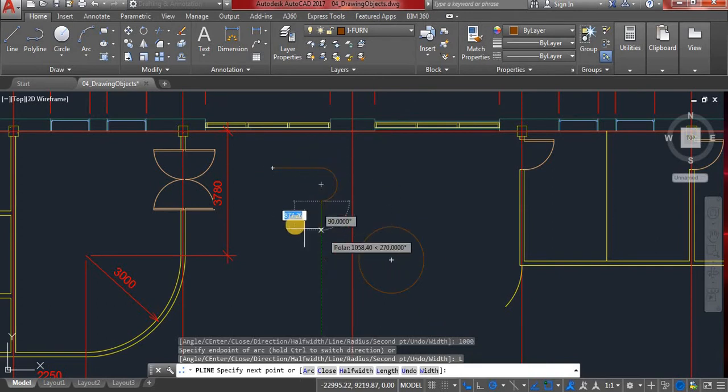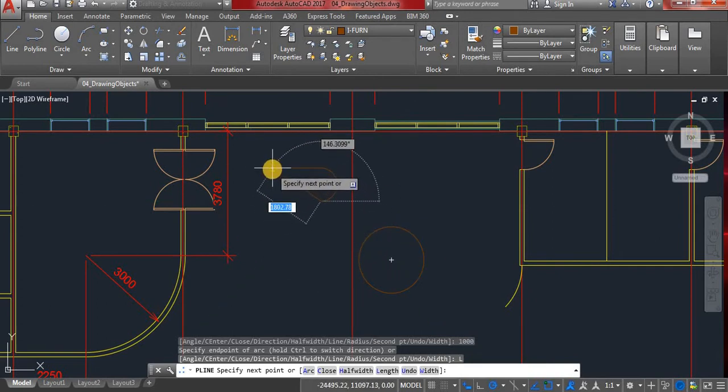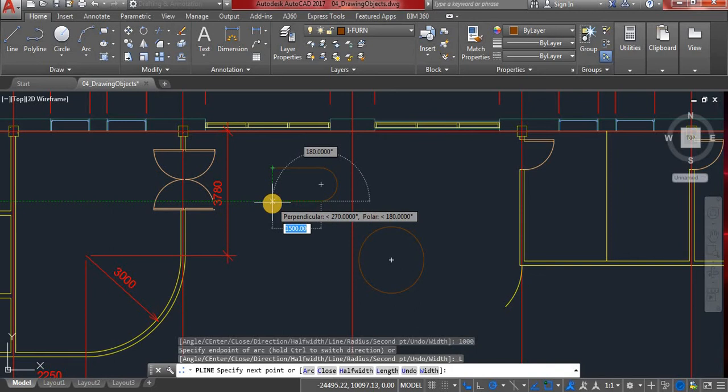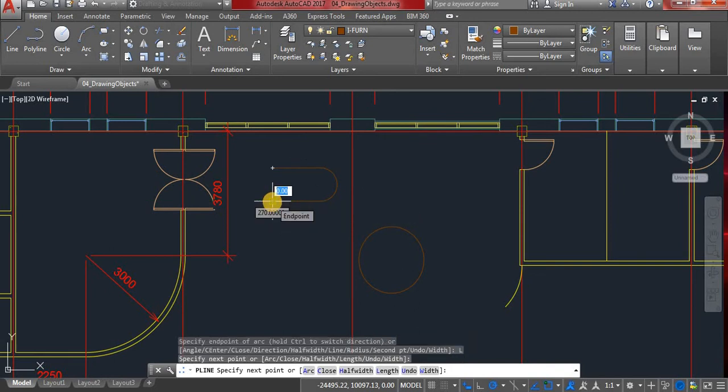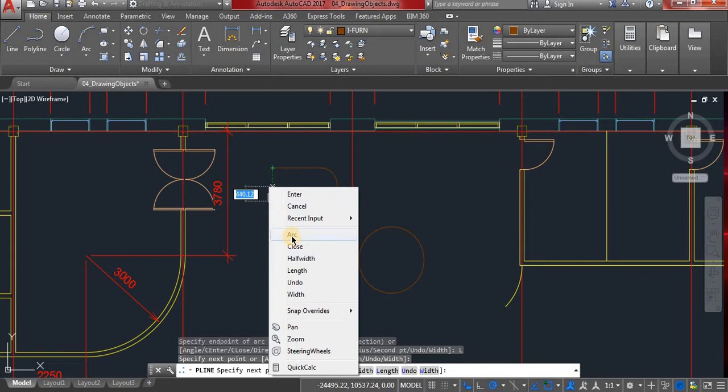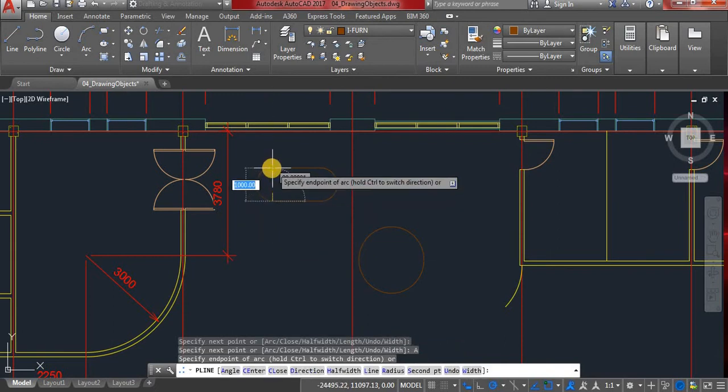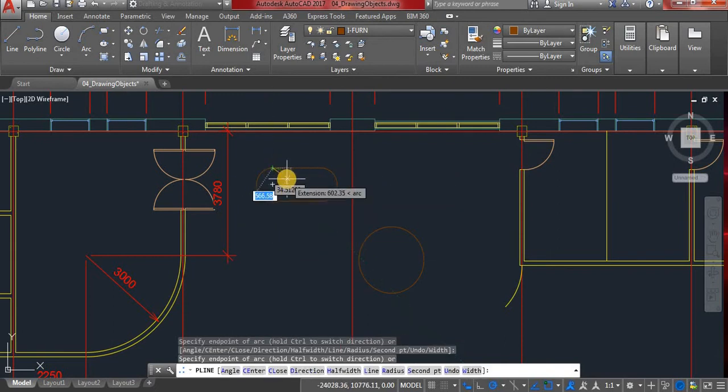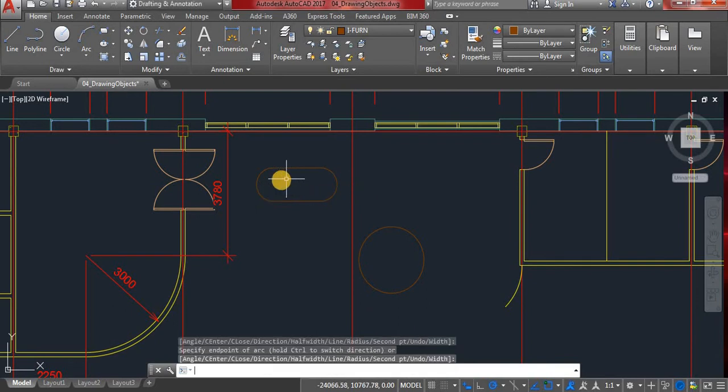Because I have my snapping tool, again, as I put my cursor near this, it will snap opposite to that point. It's so much easier. Again, I want my curve in here, I want my arc, so right click, choose arc, and it snaps to that point and click. That's it. Press enter to finish this drawing and press escape a couple times to cancel anything I have selected.